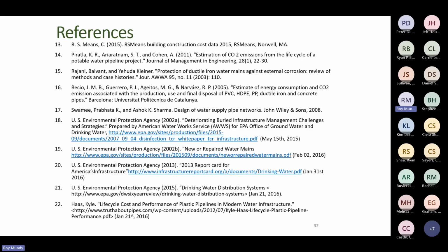And then all of a sudden we find that they first of all rolled the pipe off the truck on a cement paving or something and didn't unload it properly. Secondly, they did not lubricate the gaskets properly. They did not align the pipe properly when they were putting it in the ground and so forth. So you got to do all those things properly before you even get to the excavation itself.